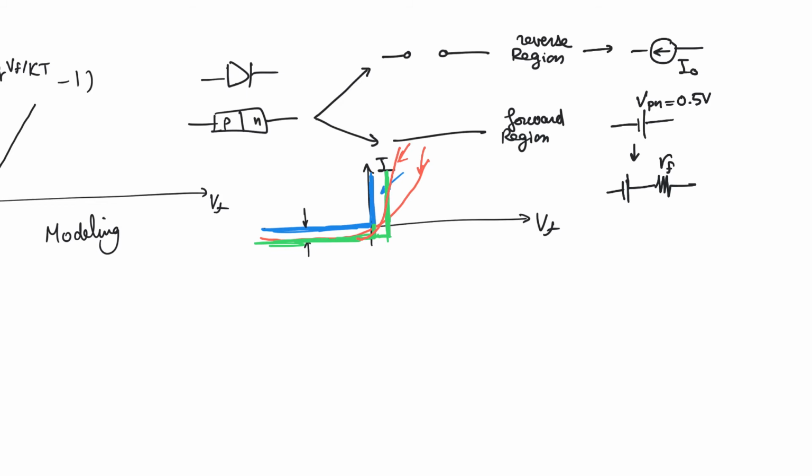This resistance is going to be small because we can expect that the slope of the IV curve is going to be extremely large because the current is increasing exponentially, but it's a resistance anyway, it's a small resistance. So that now we have something like this yellow line. And so this is obviously a much better model. Like, you know, the more we add, the better the model is at imitating the reality of the situation.